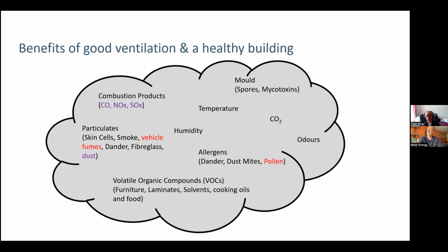Colin, just thinking about what we were talking about earlier on, when it comes to moisture balance, is traditional convection heating better or worse than radiant heating? I mean, does it matter what type, how you heat your house? Very much so. If you look at a house that's heated by gas, it gives off water vapor. Yes, and it's probably cooking more because we have balanced flues and stuff like that. But there still is a high degree of water vapor given off by the heating.